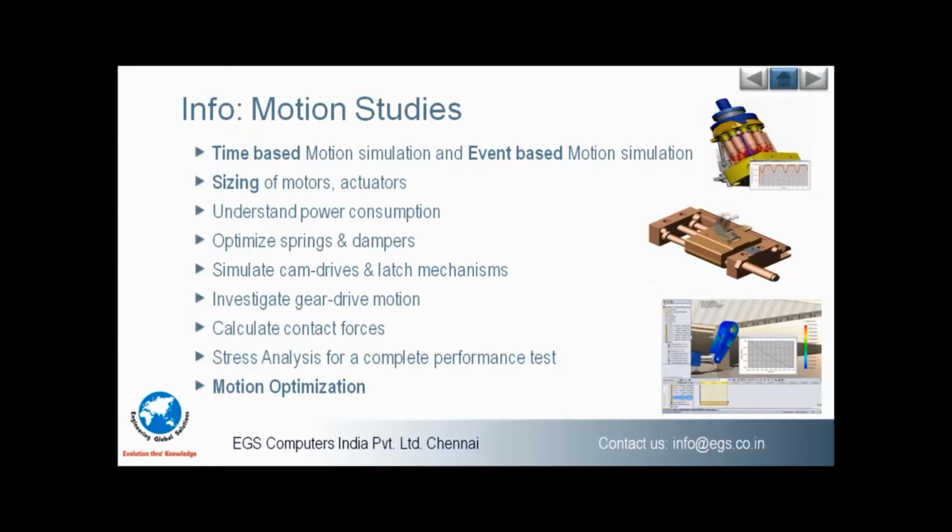And for mechanism driven options, as I was talking about the event based motion, we can directly simulate the cam drives and the latch mechanisms. A simple example is the door operation, which uses the hinge mate, and we can investigate the gear driving motion. With all these aspects, we are going to calculate the contact forces and the stresses. The user also has the option to directly import all the kinematic loads to the static study to directly study the stress analysis for the performance.